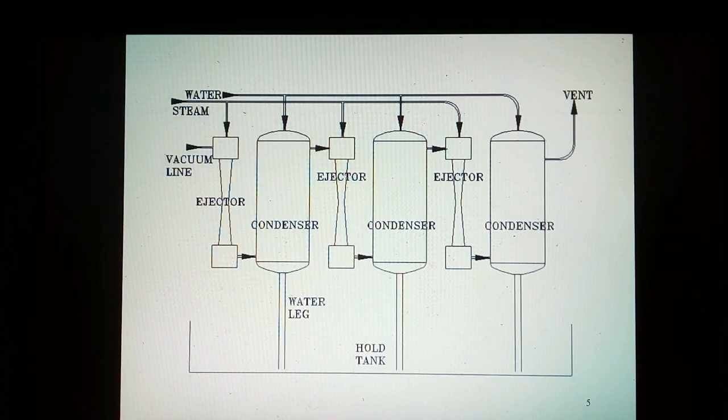The entrained gas/vapor flow and the motive fluid steam flow mix while they move through the converging section of the diffuser, increasing pressure and reducing velocity. The velocity of this mixture is supersonic, and the decreasing cross-sectional area creates an overall increase in pressure and a decrease in velocity. The motive fluid slows down and the inlet gas stream picks up speed, and at some point in the throat of the diffuser, their combined flow reaches the exact speed of sound. The stationary, sonic speed shock wave forms there and produces a sharp rise in absolute pressure.